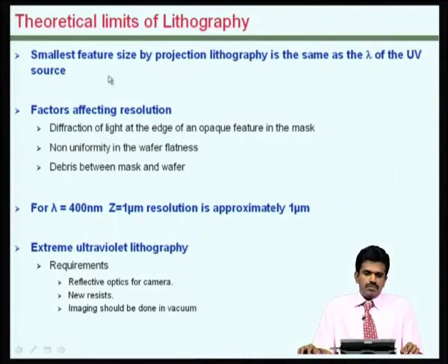One of the key parameters that affect the resolution in transferring pattern is the diffraction. As I mentioned, its effect will depend on the separation, but it primarily depends on the wavelength. So, when you really want high resolution structures, you may want to use lower wavelength beams.